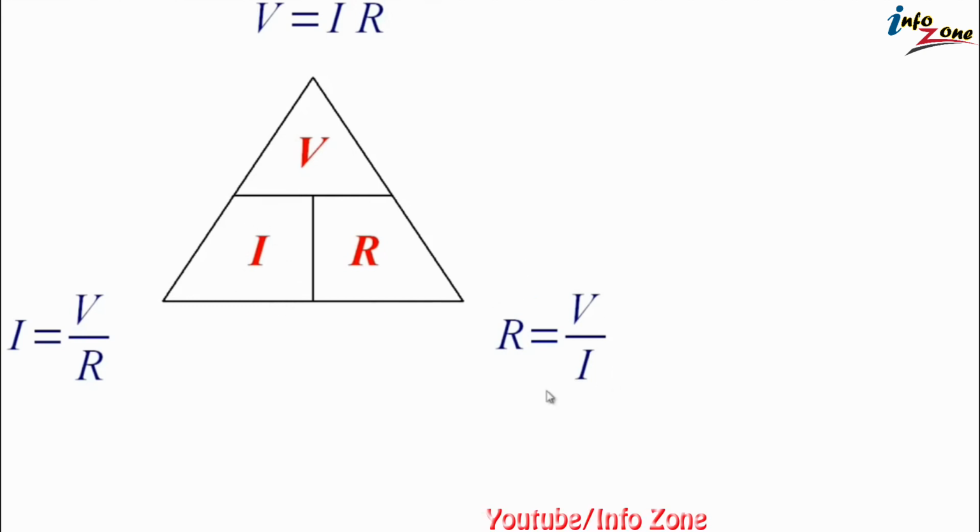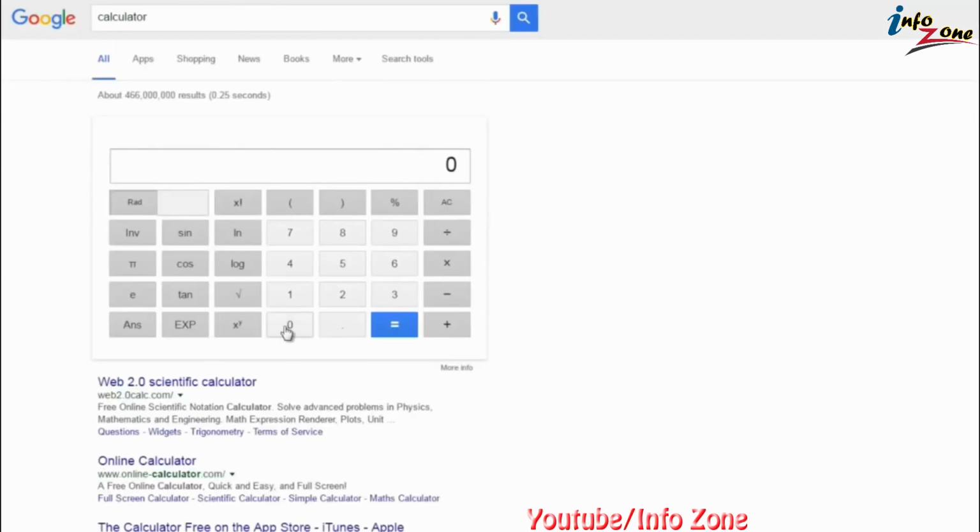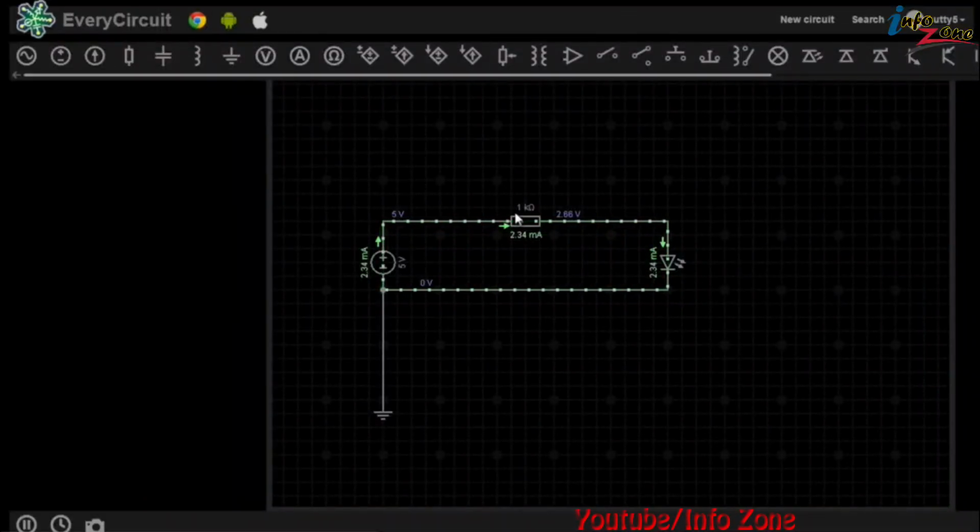So we're looking at this equation here. Resistance is equal to 2 volts over 0.02 amps. So we always write the current in amps in our equation. So if we do that calculation using a calculator and we go ahead and do 2 volts divided by 0.02 amps, our answer is 100 ohms. So 2 volts divided by 0.02 amps or 20 milliamps equals 100 ohms. So we know now that we need to adjust this resistor in our circuit to 100 ohms.